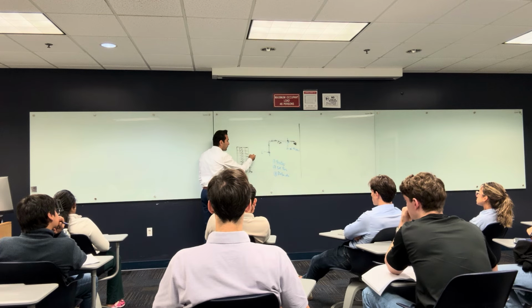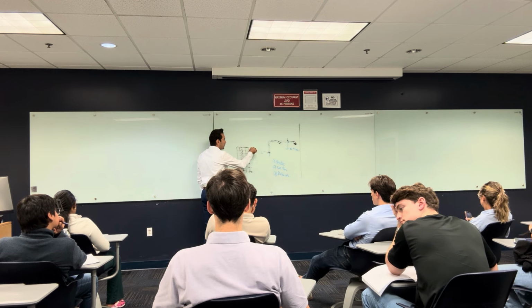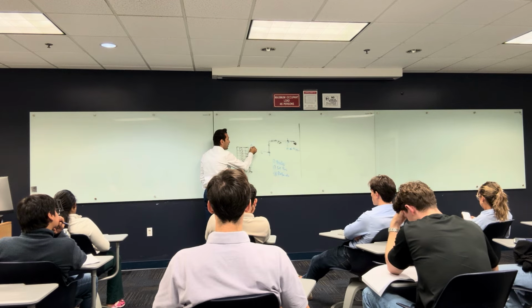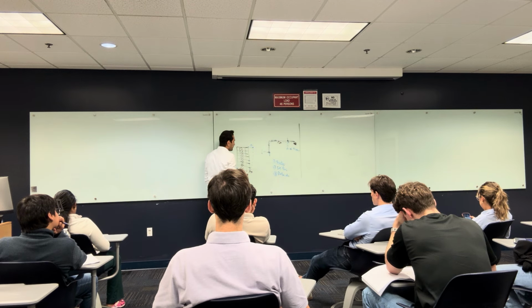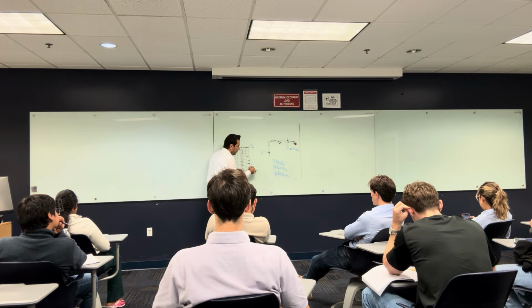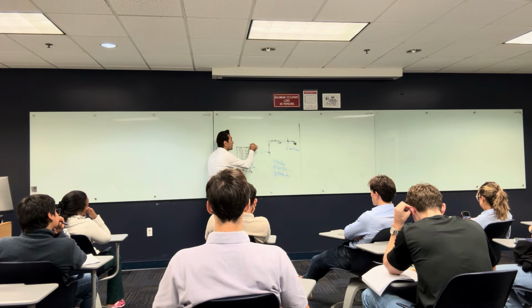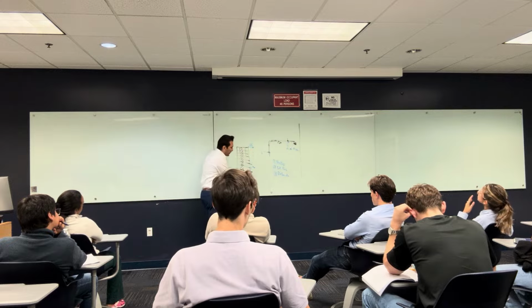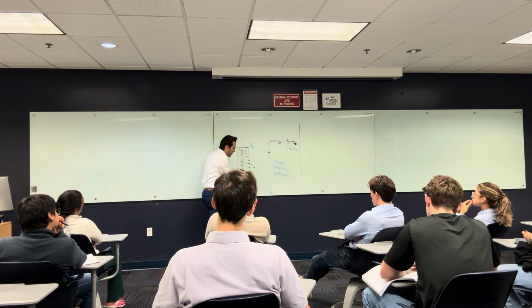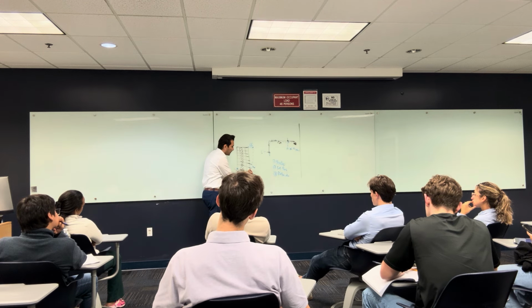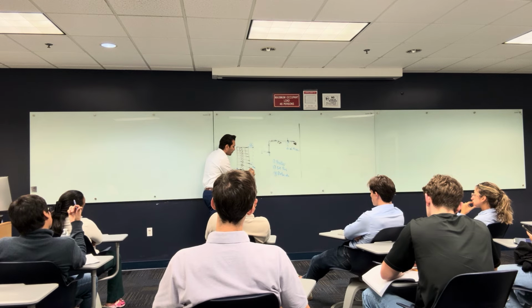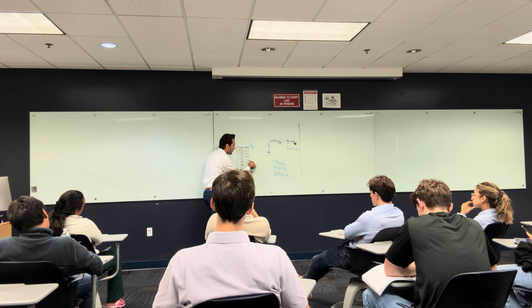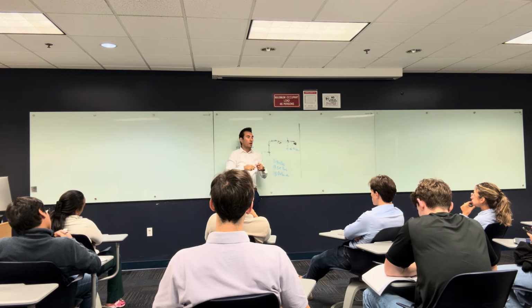Also you want to find the deformation of this structure once you apply earthquake or wind load. This delta we call the displacement. And also you want to find the inter-story drift at each level. This is called drift, delta D, from here to here. The drift is the differential displacement between the lower story and the upper story. So this is delta D1, delta D2, delta D3, but this one is the delta of the entire building. This is the total displacement of the building.